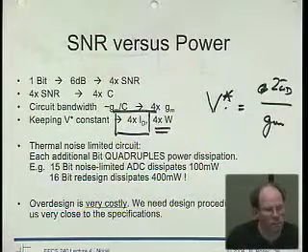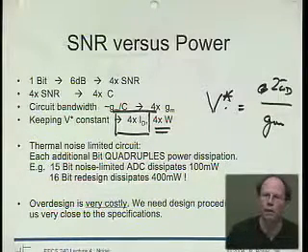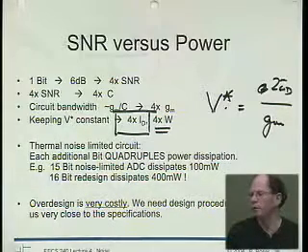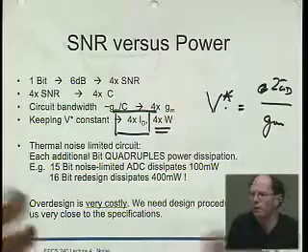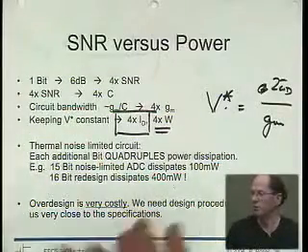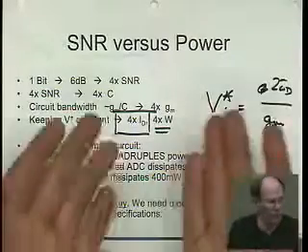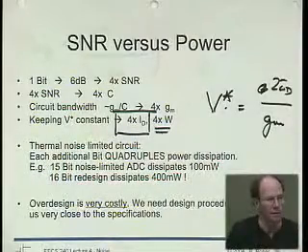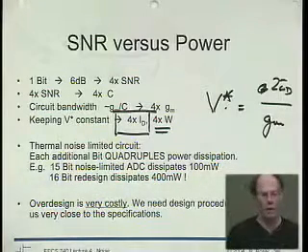Also, this problem really happens for noise-constrained circuits. If you build a circuit that needs only 3 or 4-bit resolution, you can't make a transistor that has a width of only 5 nanometers. You just can't make it. You need to make it wider, or you can't make capacitors that are only half a femtofarad. They're going to be larger. So sometimes you're not limited by noise.